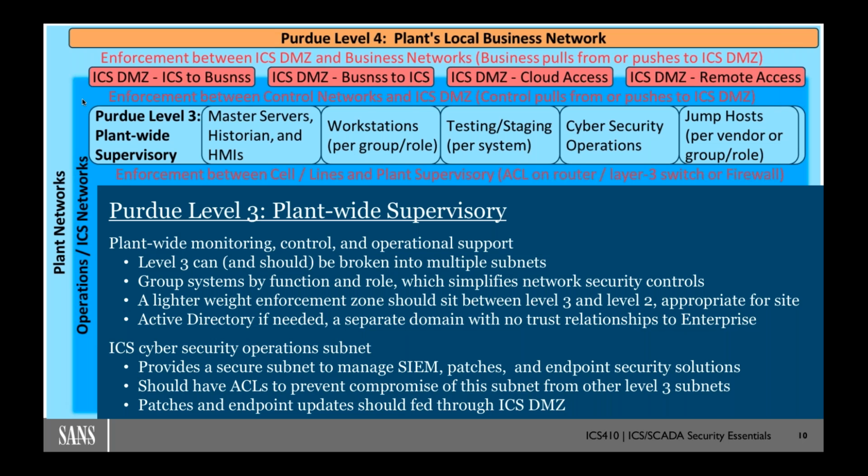Okay, this one says, what type of enforcements are used for access to safety systems? So with safety systems, as I mentioned, the safest safety system is the one that's been disconnected from any communications from the other networks, right? I love to see safety systems completely air-gapped and islanded, meaning that the only way they can be modified is an engineer takes his laptop, walks physically to the safety system, physically plugs into the safety system, and makes modifications to it, right? That's the safest scenario.